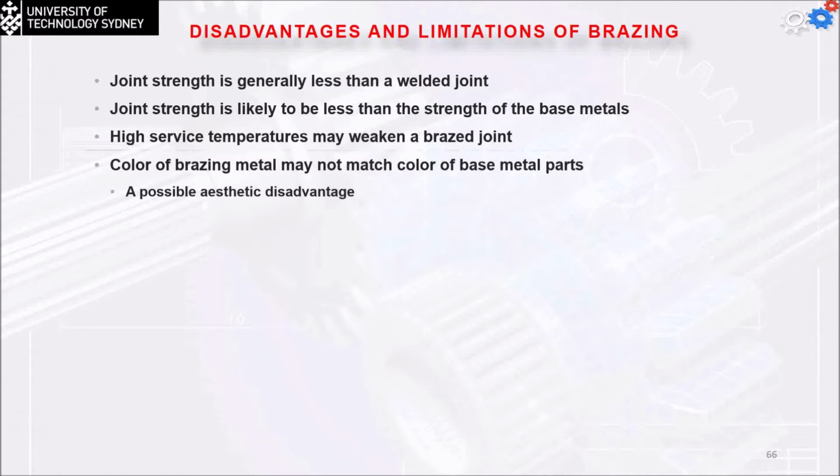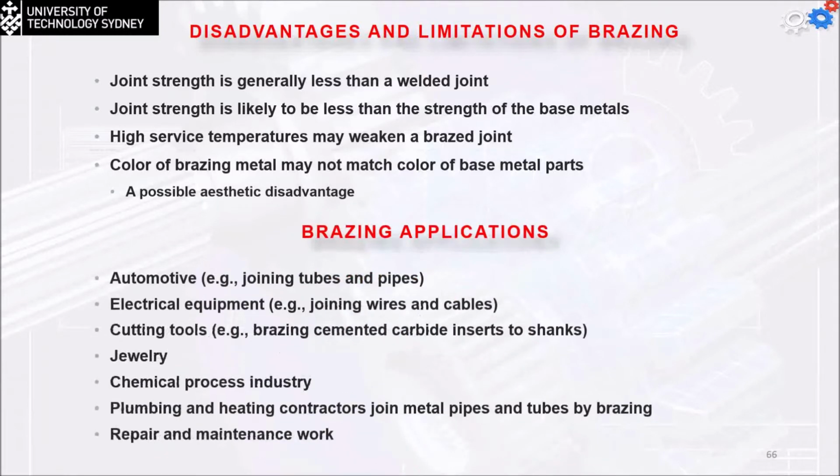The possible brazed joints are, now you can see that we're not going to put the structure at the top, like the joint at the top, like what we had in the case of welding. Now, the material will fill the cavity. We're going to have the brazed joint in the cavity. So you can have a differentiation, which is impossible to do in the case of the welding process. So the first brazed joints are going to be the butt and the lap joint.